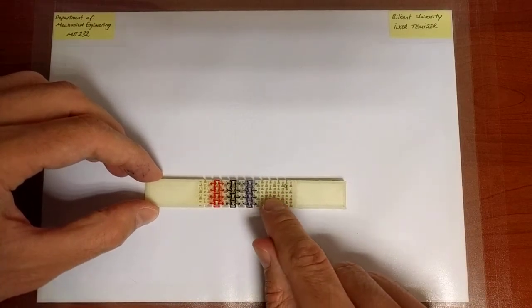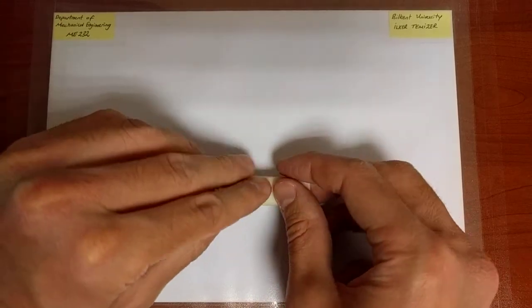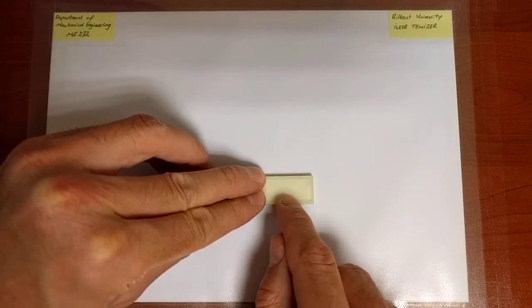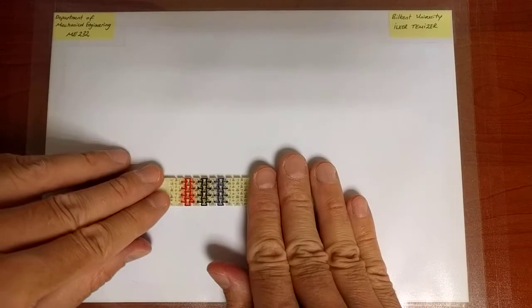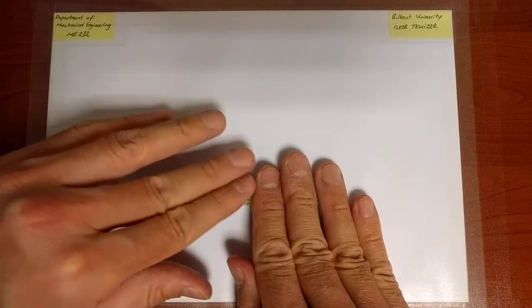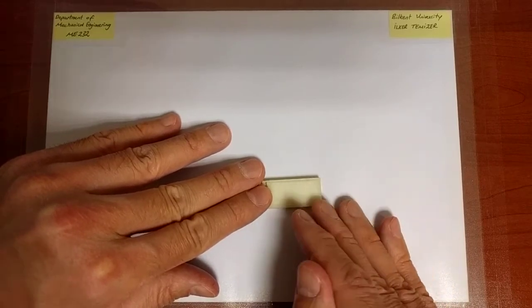This is a sample that we have discussed before. You make a cellular material. Here, the material is polymer. It is almost isotropic, okay? But here, it is porous. And in fact, it's porous such that the Poisson ratio of this part is close to being 0.5. It's incompressible. This is 3D printed.